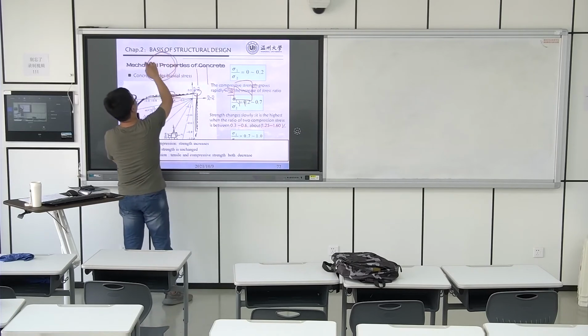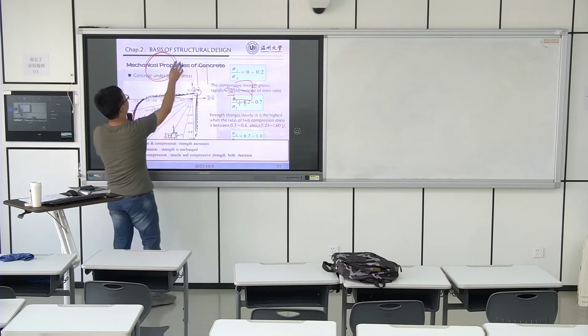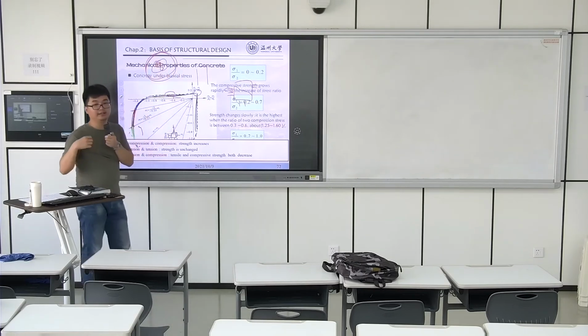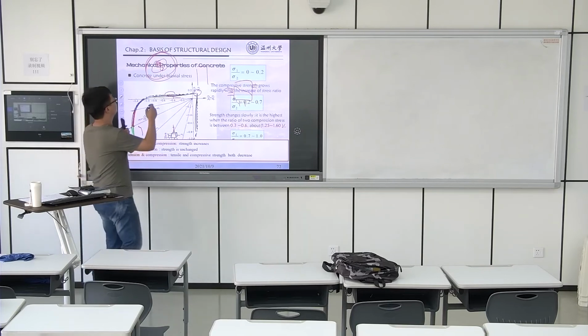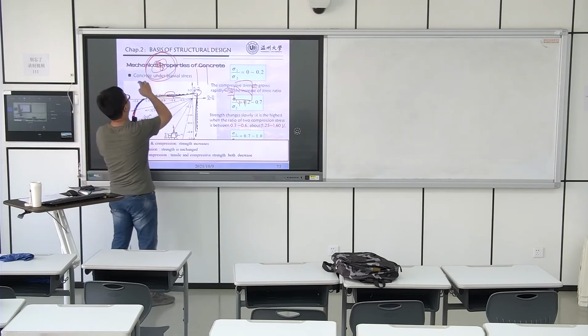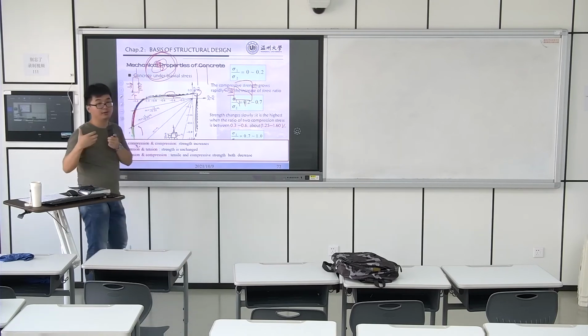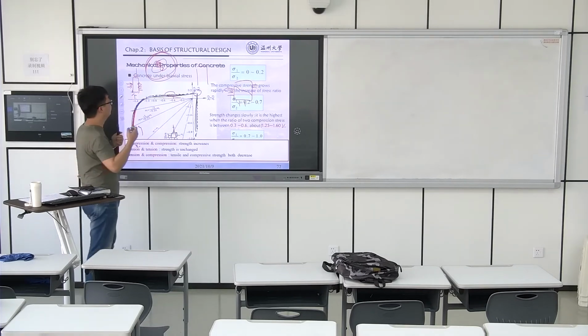It's a steel tube, and the concrete is poured in there. They confine the concrete, because the pier is under load, right? It is under this direction load, but if we give it steel here, the steel can confine the concrete. Can you imagine?